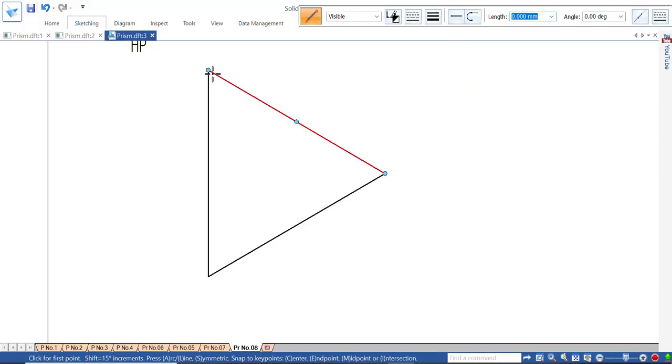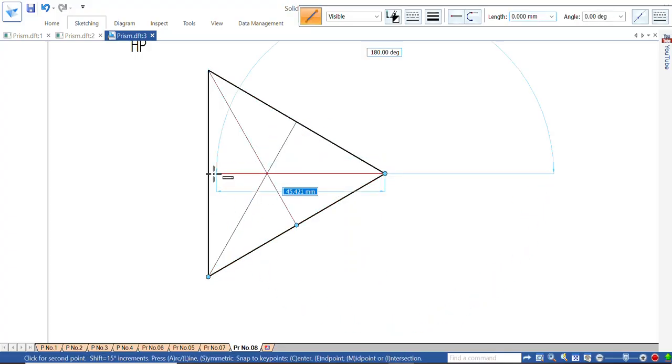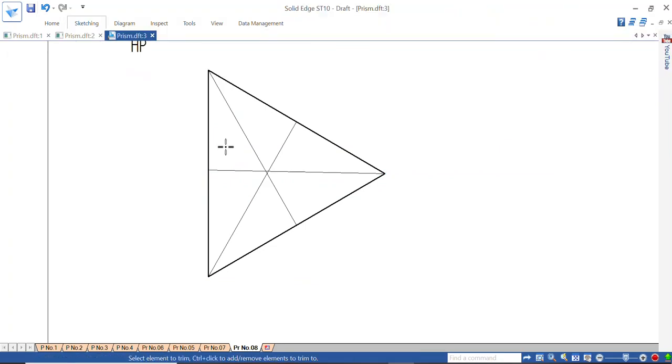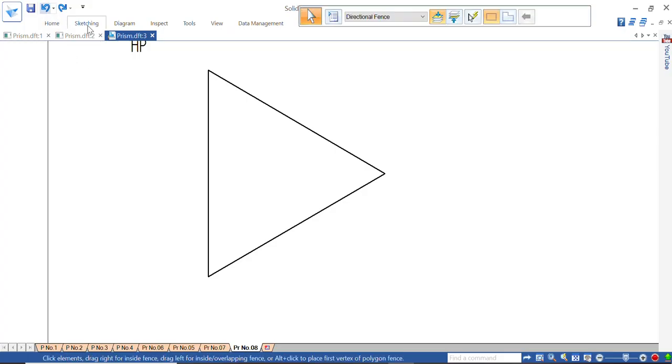Next, find the joining of each corner to the opposite face midpoint. There are 4 faces. For a tetrahedron, join one corner to the opposite face midpoint, another corner to the opposite face midpoint, and one more corner to the opposite face midpoint, and trim the 2 extra lines. From all 3 corners, join exactly to the midpoint. If it is not there, just check it, otherwise the problem won't have a perfect center point.